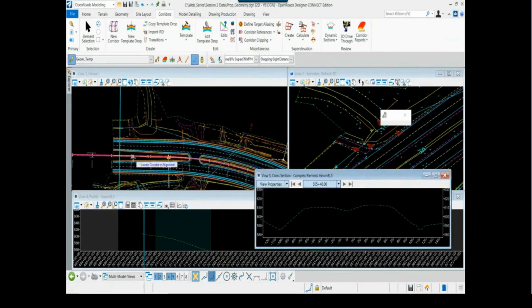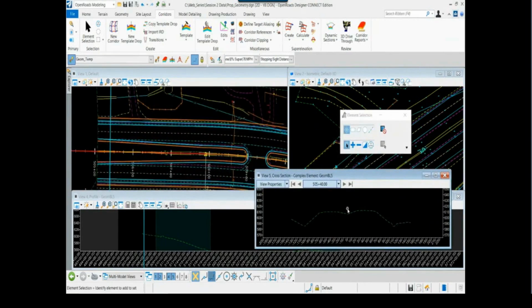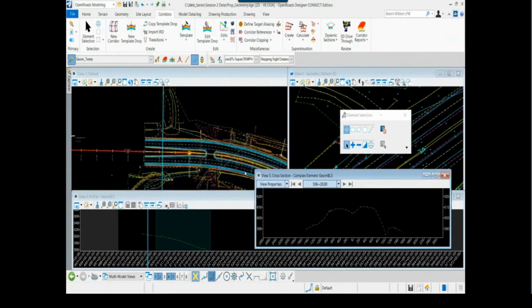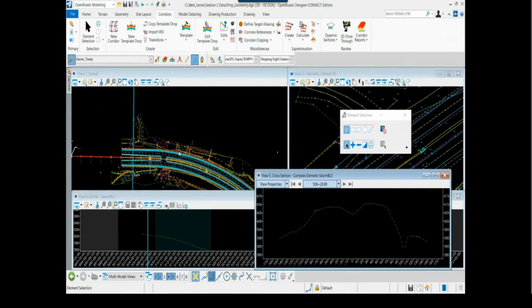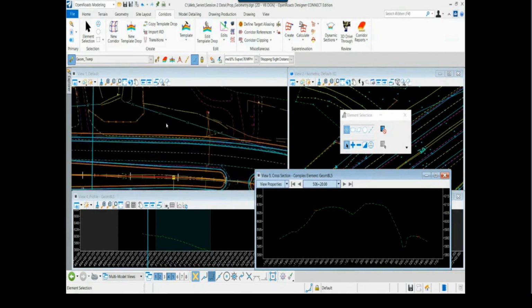Now, the sections have bearing on what I want to show you. As we cycle through here, if I exaggerate this a little bit, you'll notice, again, the elevation difference between here. We want to minimize the elevation difference between the two sides of the roadway in our new corridor. So again, we want to hold a widened inside edge of pavement. Now, how am I going to locate that inside edge of pavement horizontally and vertically?